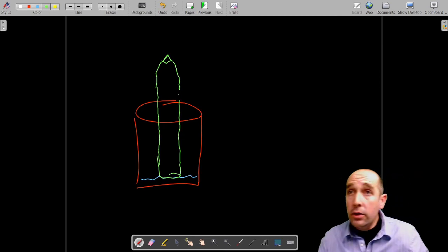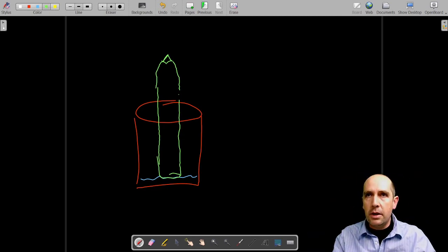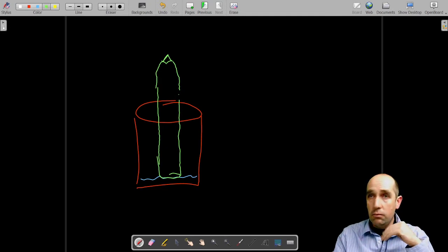And all these ingots are really big pieces of semiconductor, a single crystal, as I said. By using very pure silicon, one can produce intrinsic, very high resistivity silicon, but one can also, on purpose, add dopants into the mix.